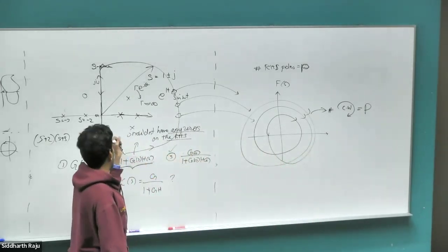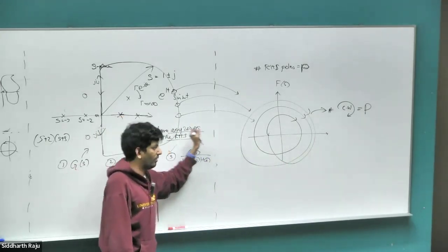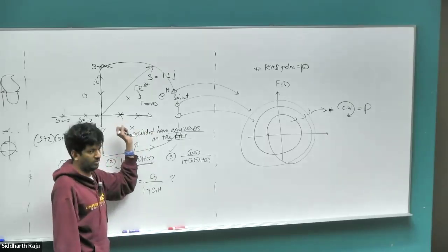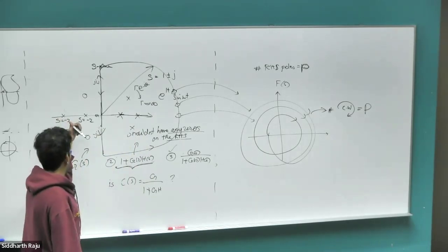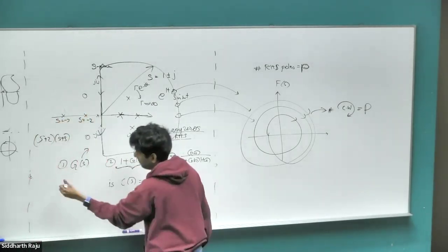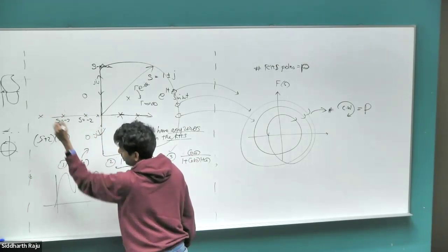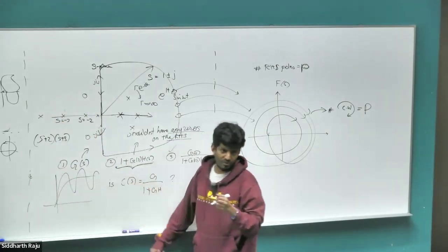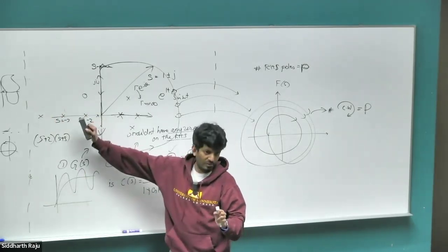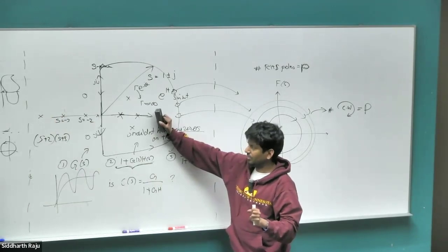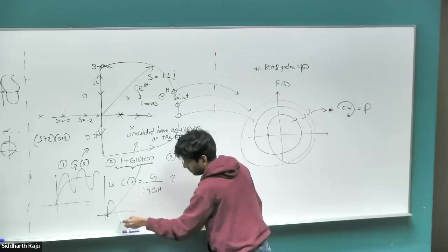It is just that I want to map everything on the RHS. Whatever is on the RHS, I want to capture it here. Because the trouble is, things that are on the RHS are what cause us trouble. We don't care what happens on the LHS. LHS would determine what the response is. If I had a 0 here, my response would be quite oscillatory. If I can cancel the pole and push it farther, then I could get a more stable response. So this would determine how nice the response looks, but it does not determine the stability. The only things on the right hand side are the ones that are troubling, because they will determine whether it looks like this or whether it looks like this.